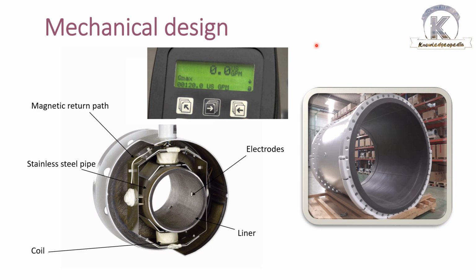That is the HMI and display. HMI means human machine interface. That means you can adjust the different parameters through the push buttons or any other medium like a HART communicator and all. That can be mounted integrally, which means it could be mounted just above the flow meter, or remote, depending upon the installation situation. Remote means the transmitter could be separated from the sensor through a cable.